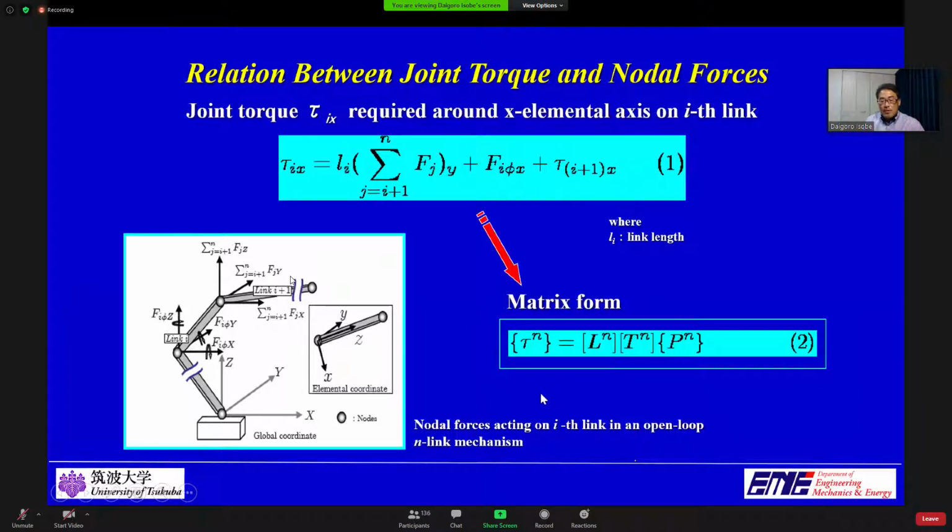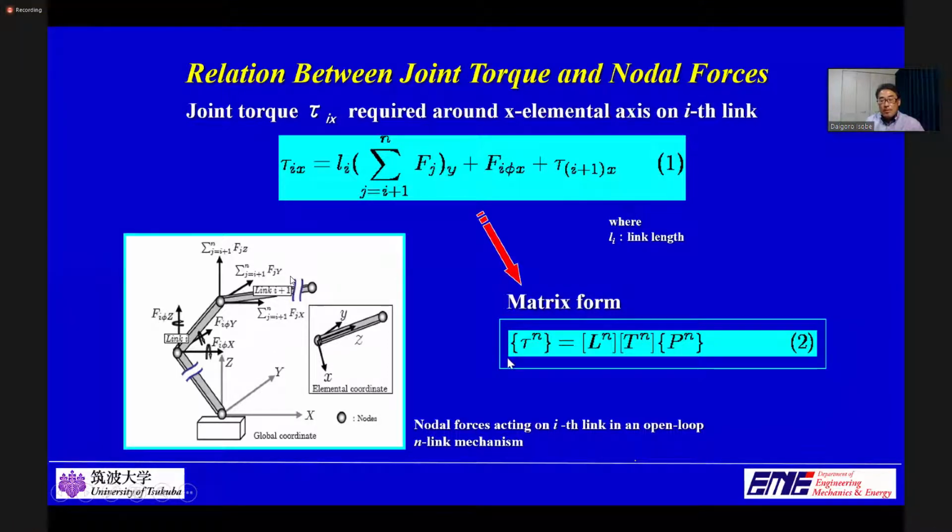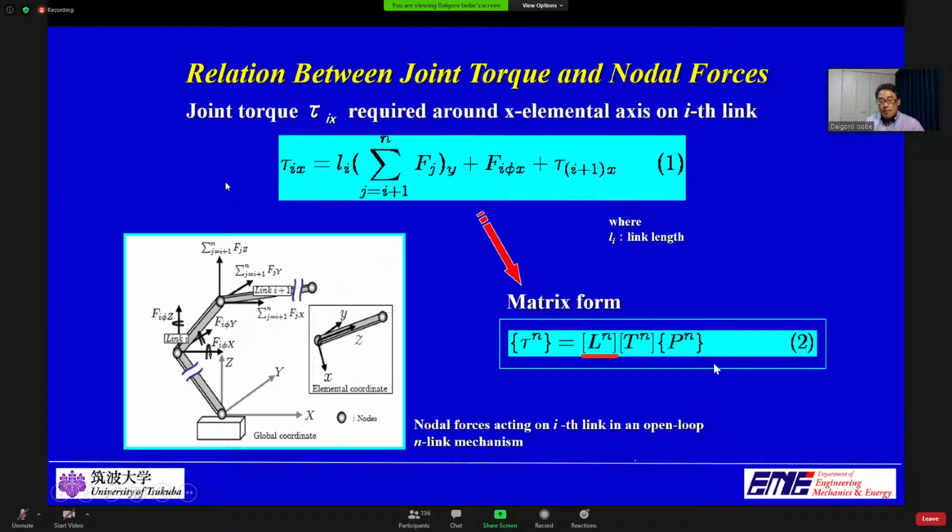The equation is completely separated into terms of different parameters, and each matrix has a clear physical meaning related to the modeled link system. The separation of the parameters makes the equation highly expansible and flexible, and so the scheme becomes applicable to complex link systems without difficulty. The member length matrix Ln, for example, contains components in the dimension of length which play roles in converting forces to torques.